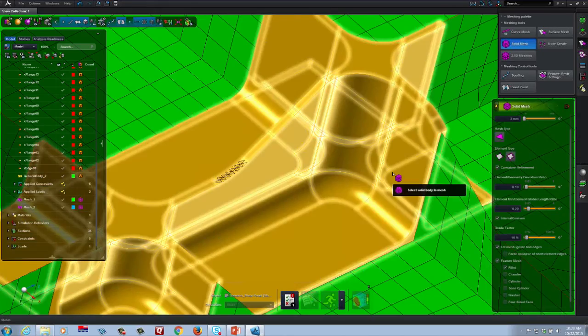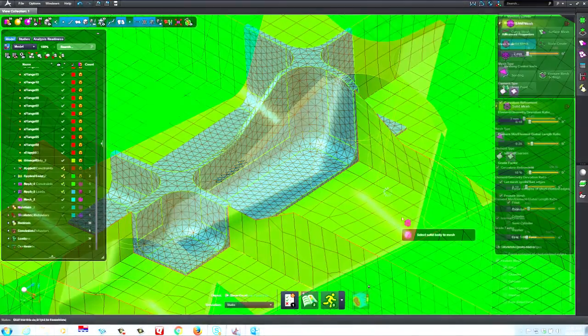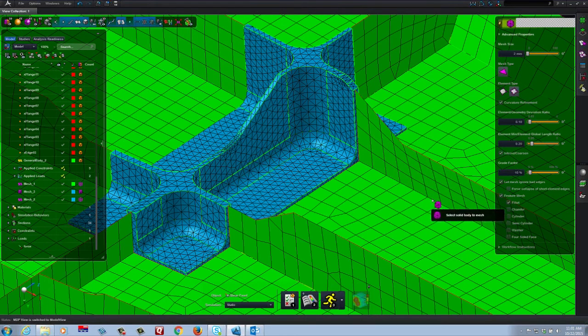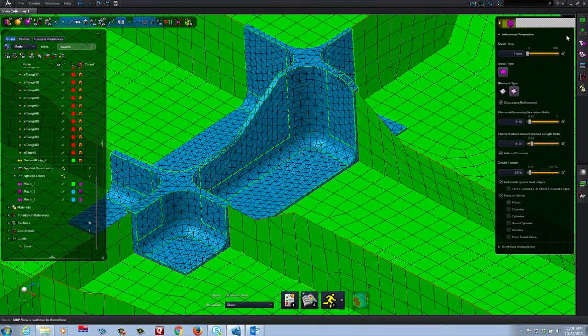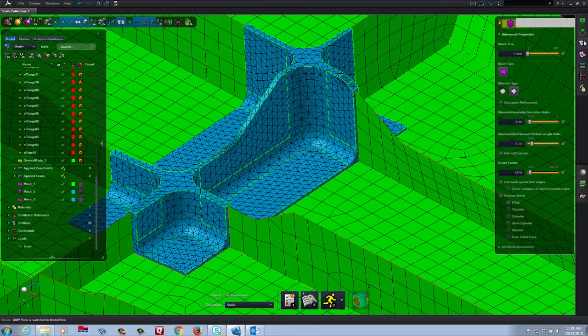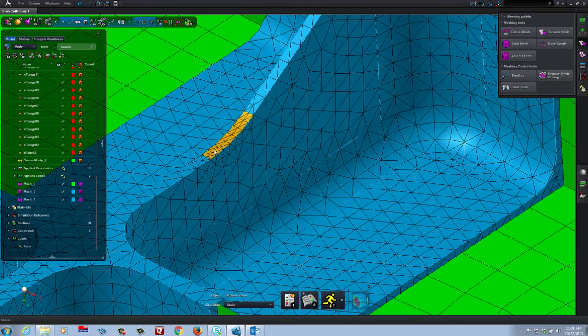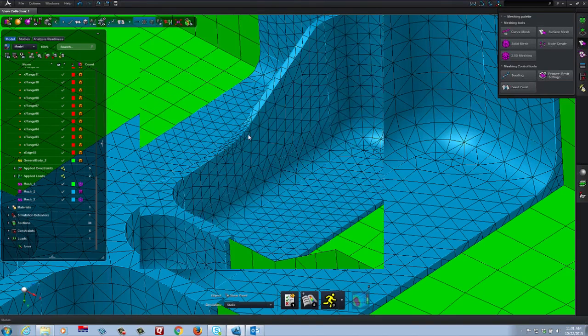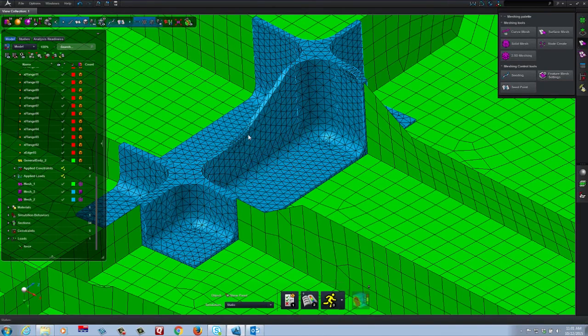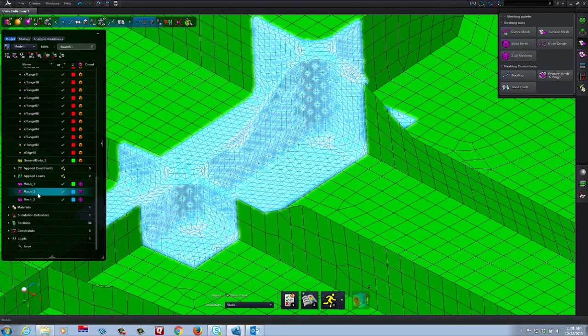And I'll select my solid. All right, so we've got our mesh here, and if we review our mesh just a little bit, what we will find is that we actually have captured the feature-based mesh settings that we were really interested in, by having like 3 elements on the small fillet, having like 6 on this fillet, and we've even captured our refined mesh in this area where we created a seed mesh, because this was the critical area. This was the area that we were interested in.